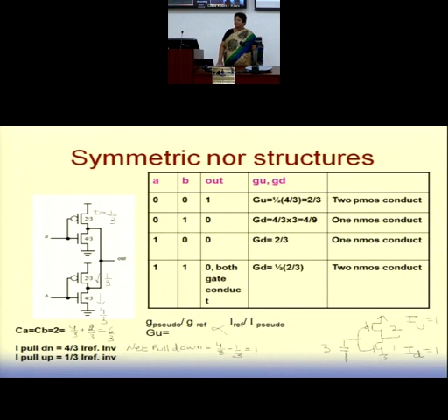You can find out the G values and then take a path of asymmetric logic gates and apply all the principles of delay minimization, and the number of stages that you want to optimize. All the concepts you can apply to the symmetric logic family. Symmetric logic can be taken as an extension of pseudo. It behaves like a pseudo NMOS gate.